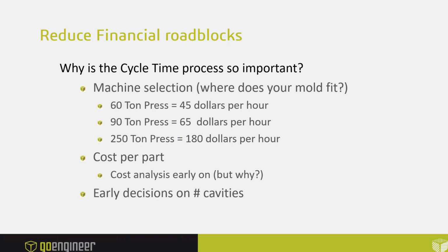When we look at cycle time, it's going to tell us a couple of things, right? When we look at SOLIDWORKS Plastics per se, it's going to tell us how long it takes to fill, how long it'll take to pack, how long it'll take to cool, right? And so those are three good indicators about how long the actual filling process is, the packing process, and the cooling process. So that gives us what's going on inside the machine.